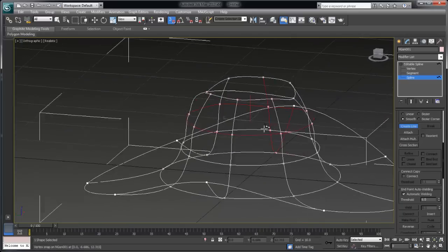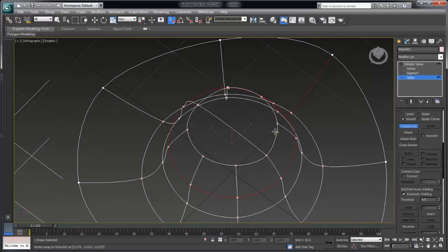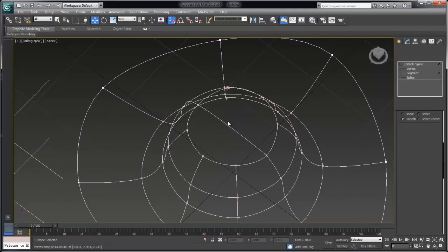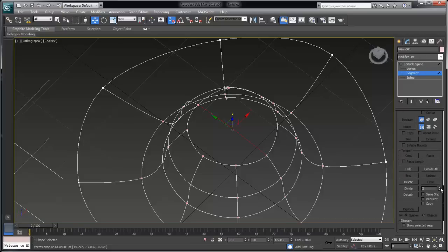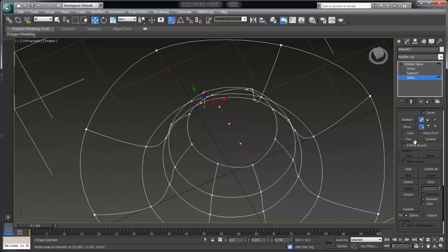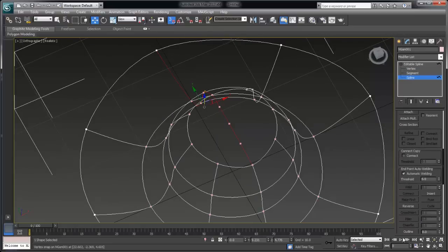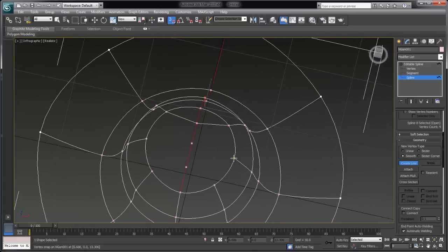You see that it has adjusted the curves of that, the interpolation of the curves. But you notice I count my regions. 1, 2, 3, 4. There's that. I'm going to subdivide that line a little bit because I want to add some more topology in there. And use my vertex snaps, go in there. And by subdividing that middle segment 3 times and then creating these additional splines, I'm creating 3 and 4-sided regions there at the top of the hat. You see there's 4 there, there's 3 on the ends. So those are all legal regions.